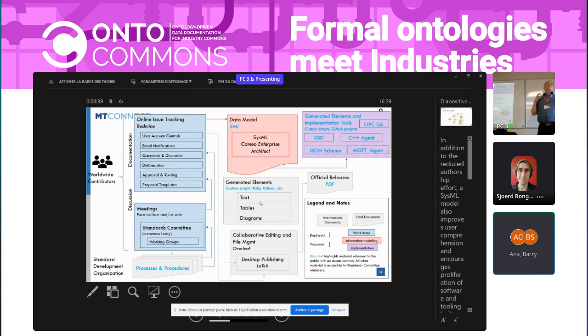We decided to take this standard and make it so we were a communication standard as well, so we could get data off the machines using REST, but we, a long time ago, divorced ourselves from representation and protocol. So we also have an OPC UA companion spec, we support MQTT, we're going to support SparkPlug-B and trying to do the first companion specification with SparkPlug-B, see if we can get them to do that.